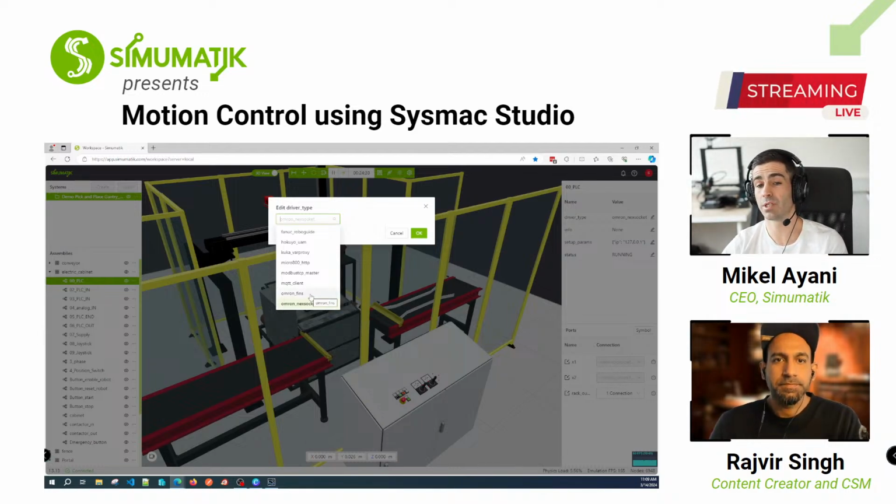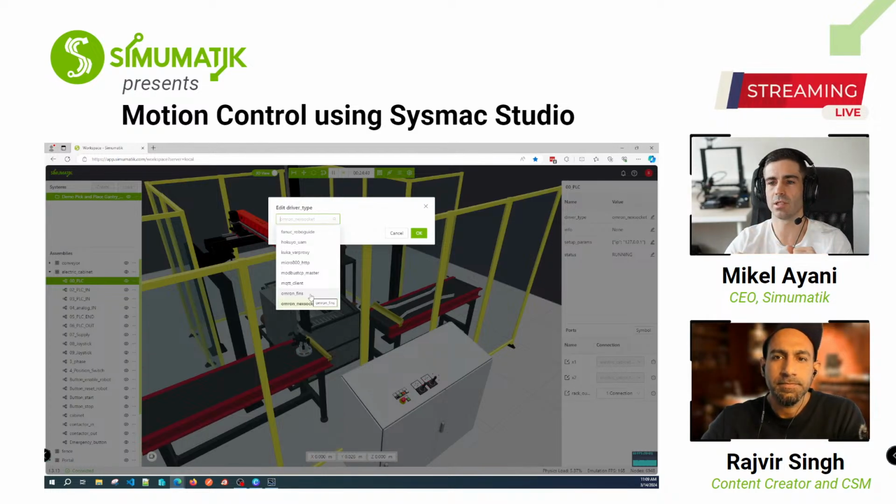As we can see here, we also have the Omron FINS, and if we check the documentation, we will see that in order to read and write variables in the PLC, you need to use addresses. They are different memory areas, so check the manual as usual.